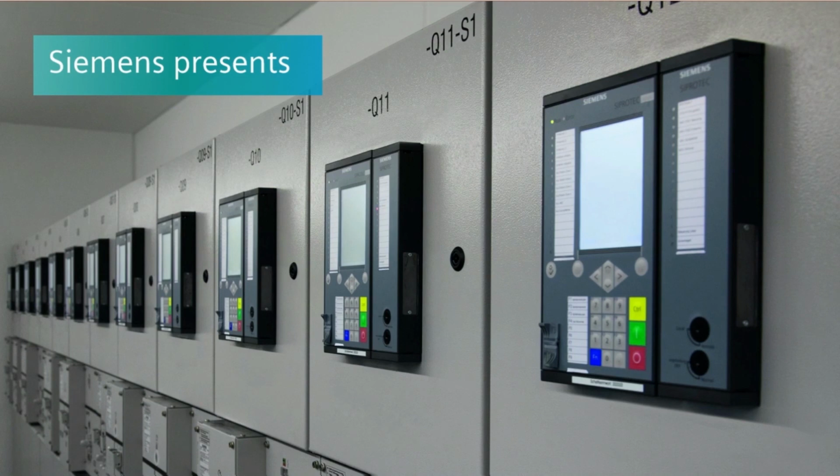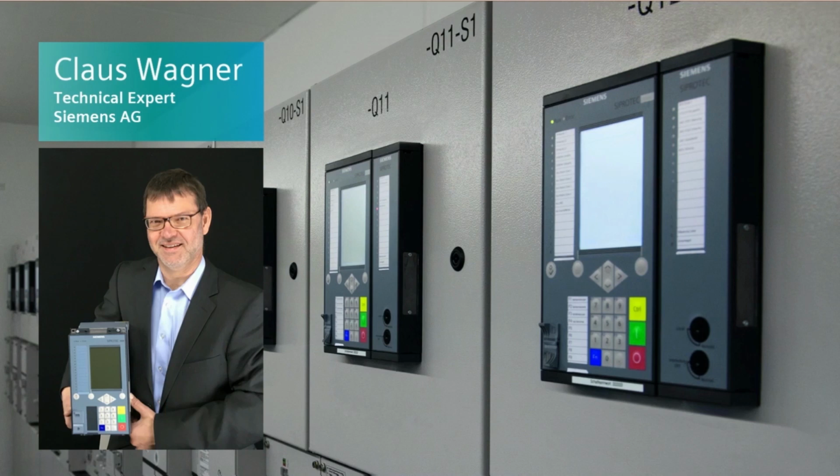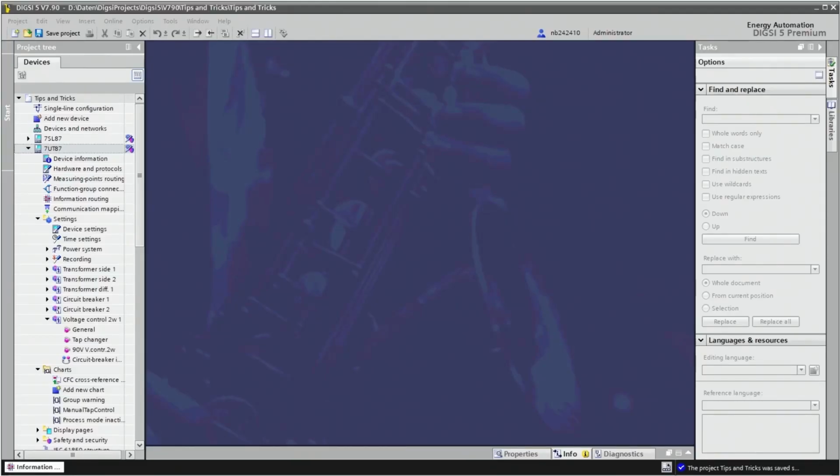Hello and welcome to DIGSI 5 Tips and Tricks. My name is Klaus Wagner, and in this video I would like to show you how to change the switching authority if no key switches are available, using only one function key. Additionally to the key switches, the switching authority can be changed via protocol or via binary input. I would like to show you a very quick method to use one function key to toggle the switching authority from remote to local and vice versa.